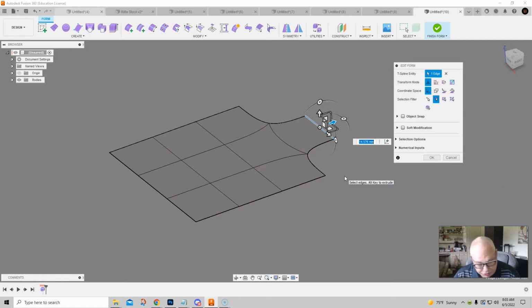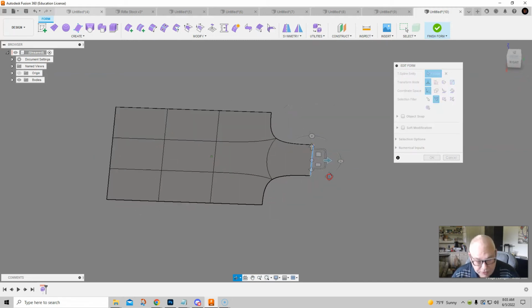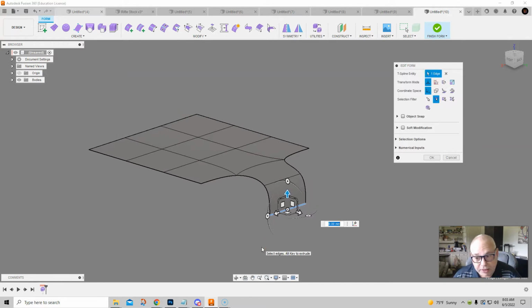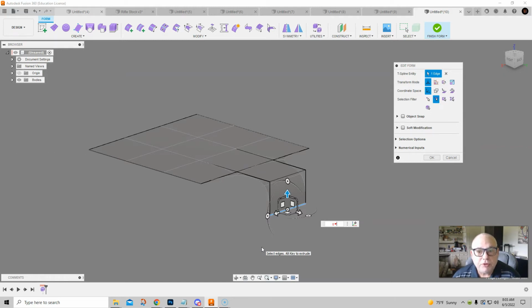Now some speed keys. By default, when you go into subdivision surfaces, T-Splines, what's happening is that we're holding the Alt key and then we can clone. By default, everything is smooth, so your speed keys here are: Alt-1 goes into your box mode, Alt-3 is smooth mode, and Alt-2 gives you the smooth with the base shape on top of it.